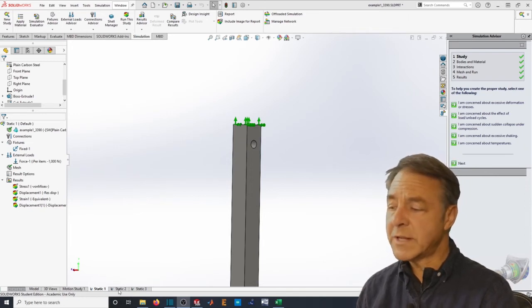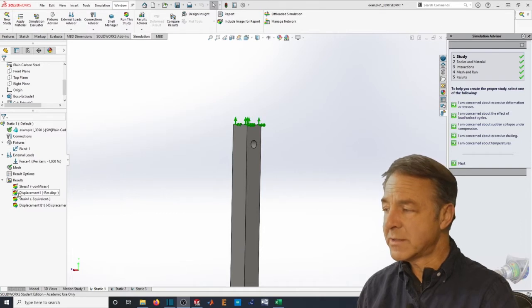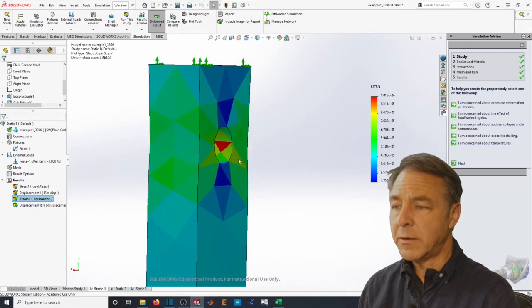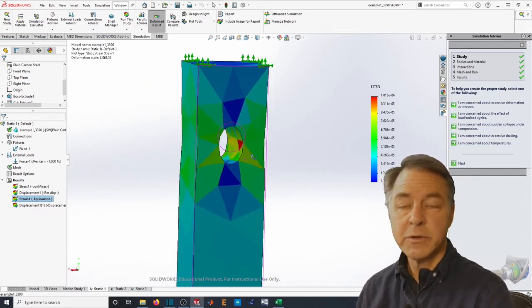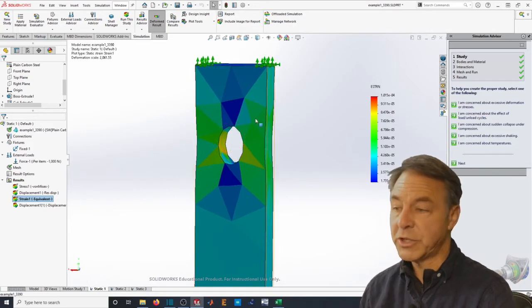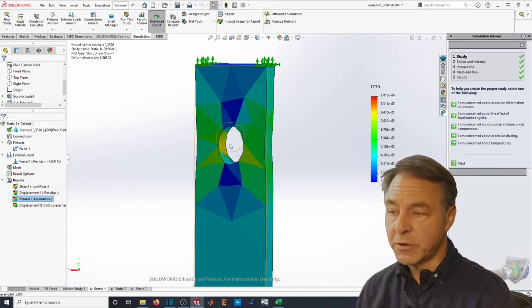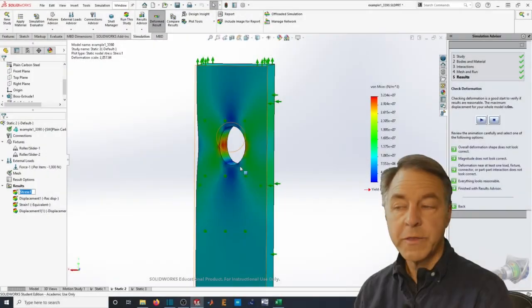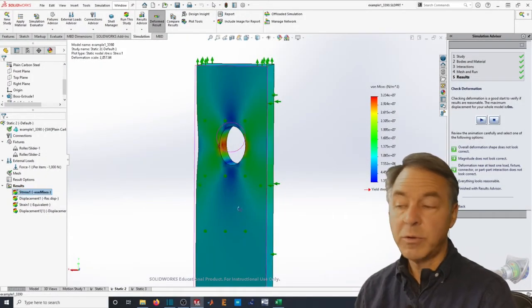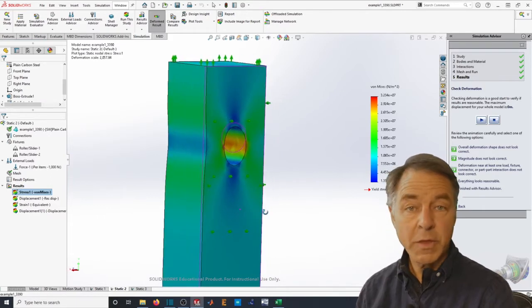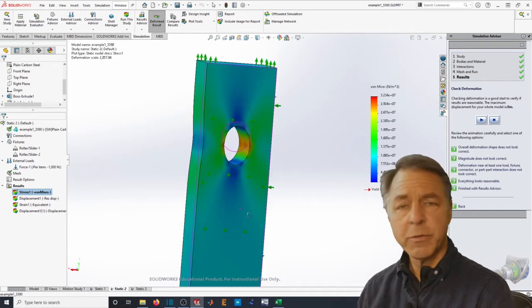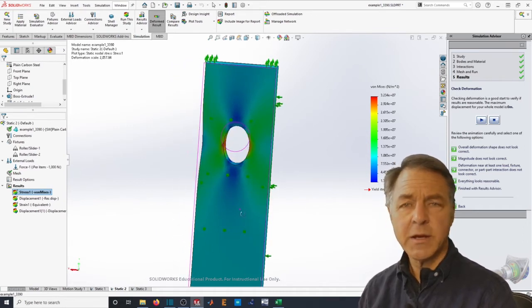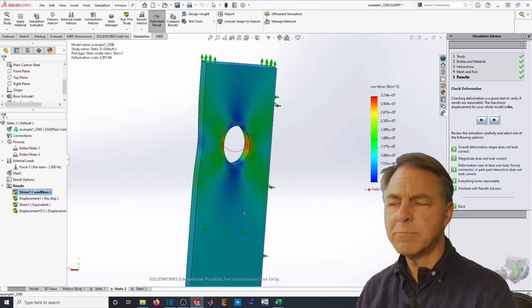So what this is telling me is that whether it's the solution in this case with the fixed plane at the top, which I've done by meshing it around, and this is a very coarse mesh, or whether it's the same problem, but this time using 3 planes as the fixtures, as roller supports, both of these solutions give me a result that wasn't really making sense.